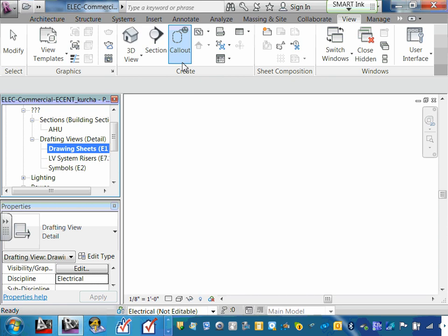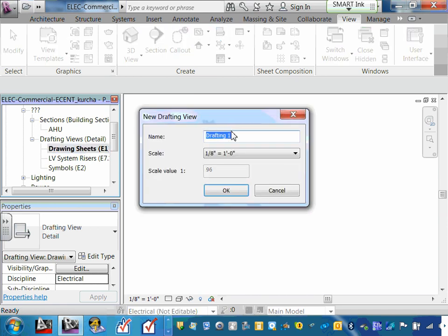Let's do one more, guys, and you're going to see why I'm doing them. Click on another. This one I'm going to call lighting fixture schedule. Lighting fixture schedule, that will be in E. Anybody remember? E9. Lighting fixture schedule. Cool? All right, hit OK.